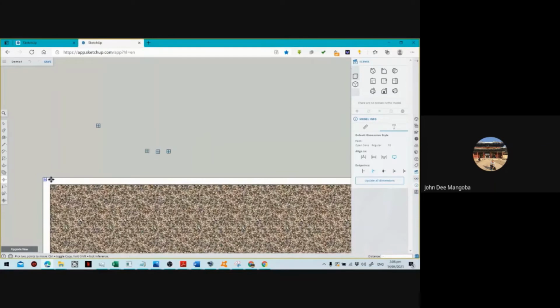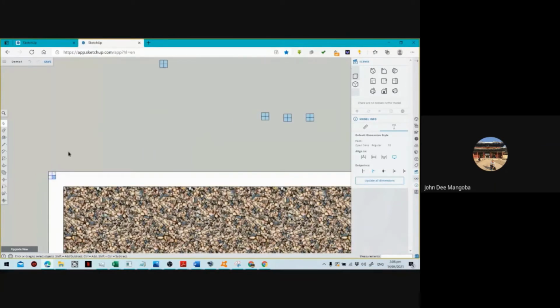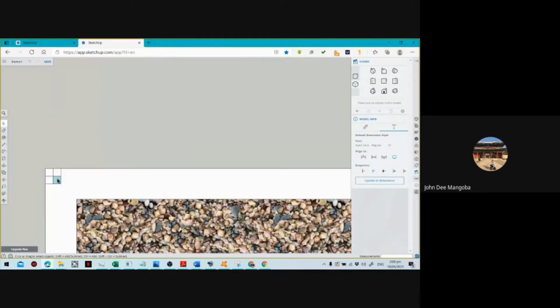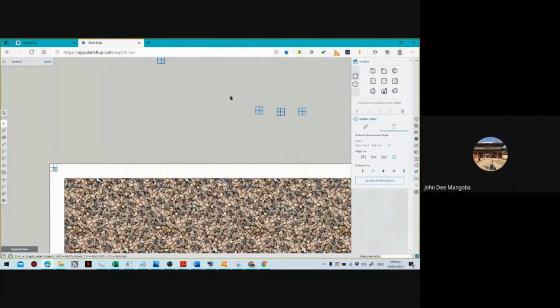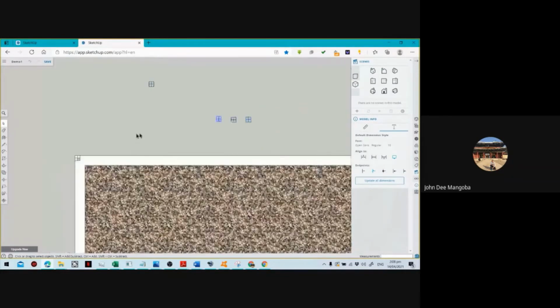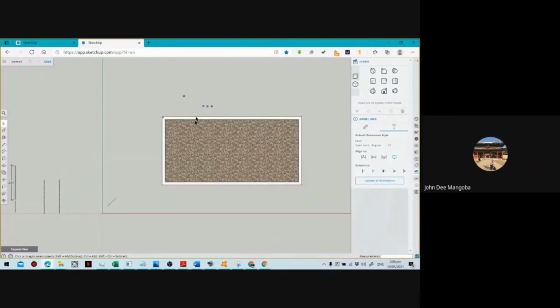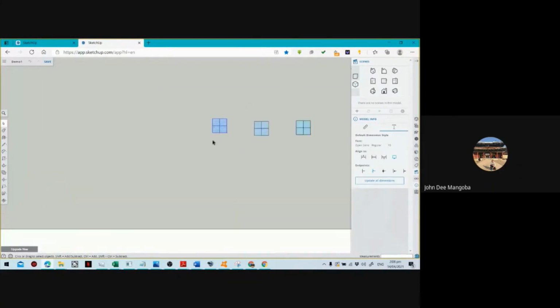So, that's easy. So, we have that ready there. Next. For this one, let's place it at the bottom left. So press M, click on the bottom left corner of your square.